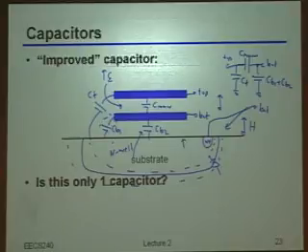And so that means that now, okay, maybe I got rid of this capacitance from the bottom of the metal to the top of the substrate, but instead I've replaced it with capacitance from that junction. Now that could indeed be a good thing. Depends upon the spacings, the relative doping levels, and things like that. But actually, if we take this just one small step further, I claim we can do even better than this. The way you do even better is the following. Instead of tying that to the bottom, let me tie it to just some bias voltage. But let me do that through a really big resistor.